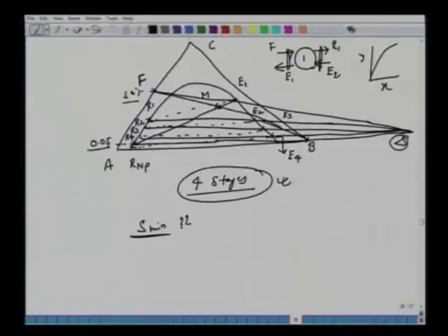That time we recall tie line or equilibrium curve coincides with the operating line. The same situation we had in case of distillations. The two lines coincide, then we require infinite number of stages and driving force goes to 0. So here question also comes, is there any possibility of operating line coinciding with this equilibrium curve? Look at the curve again.